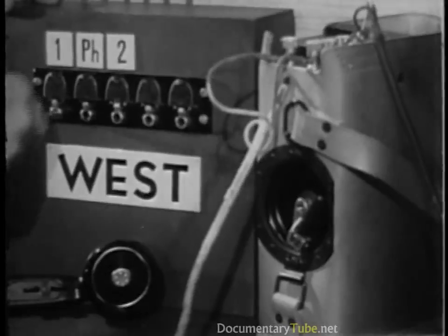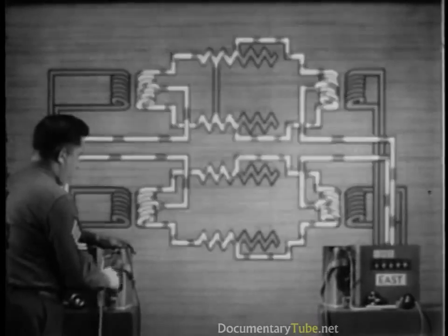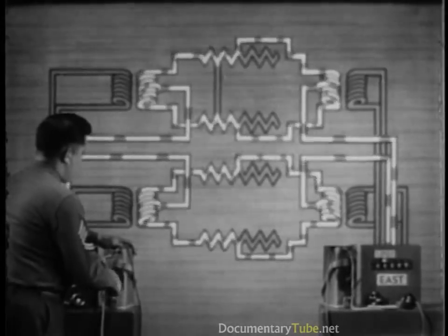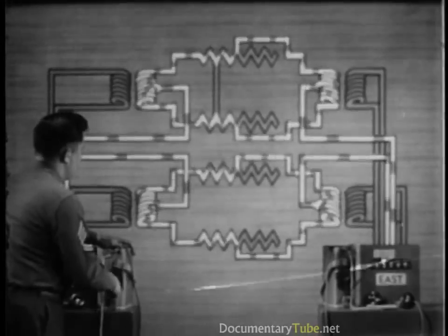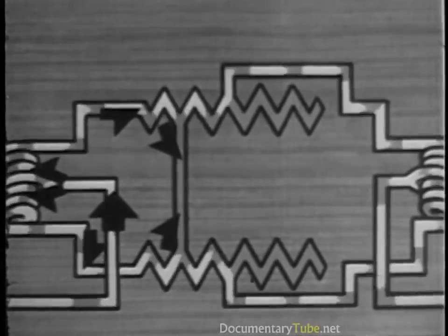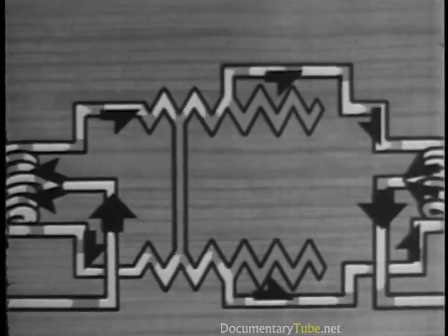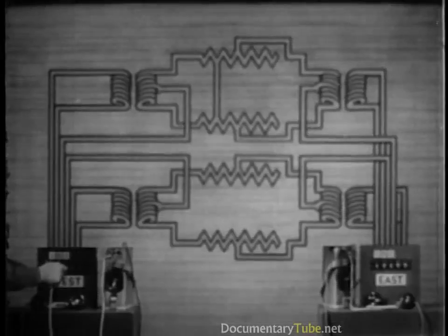When we ring on the phantom, however, we can see that it is unaffected because the 2 halves of the phantom current are traveling in the same direction. When they reach the short, they buck each other, and no current flows through the short. That is exactly what happened in the telegraph channel of the shorted simplex.